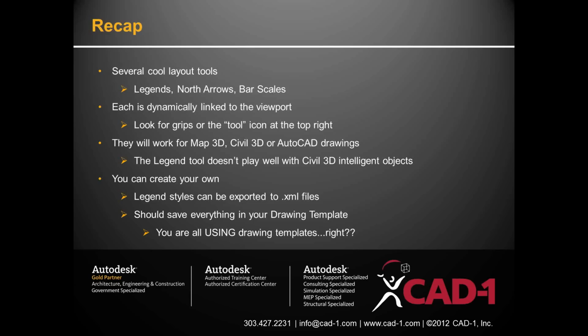They will work for maps, Civil 3D, AutoCAD drawings, but the legend tool doesn't necessarily play well with Civil 3D objects, and it will work for AutoCAD, but you've got to do a lot of setup to get these maps built inside of AutoCAD. And you can create all your own legend styles. You can create those pretty easily using the table commands.